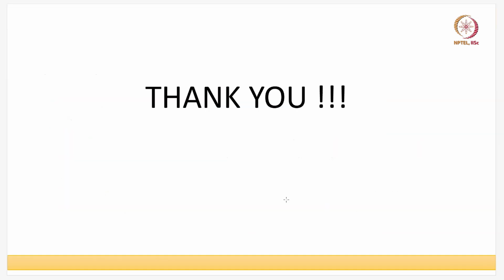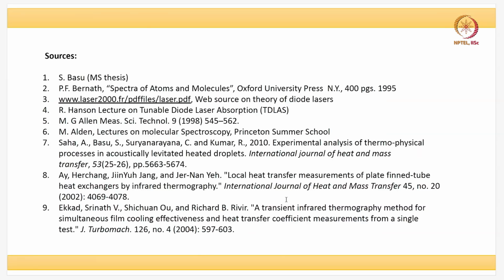The last thing I want to mention before we end this lecture is that it's a non-intrusive method. Therefore, we don't need anything to poke the flow or the system with. Thermocouples and other things are point measurements, so they will not pick up any spatial variations. They might pick up the temporal part, but not the spatial part.